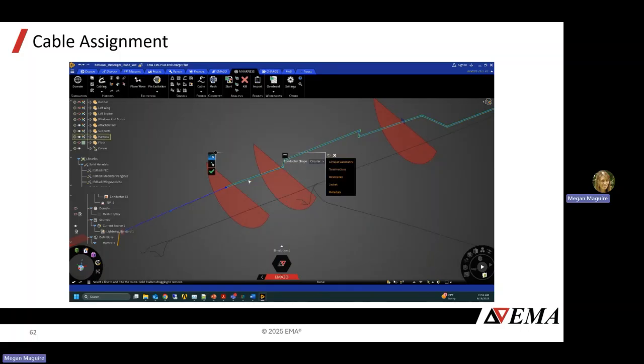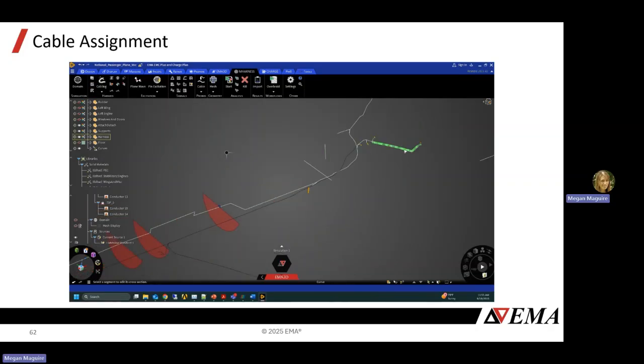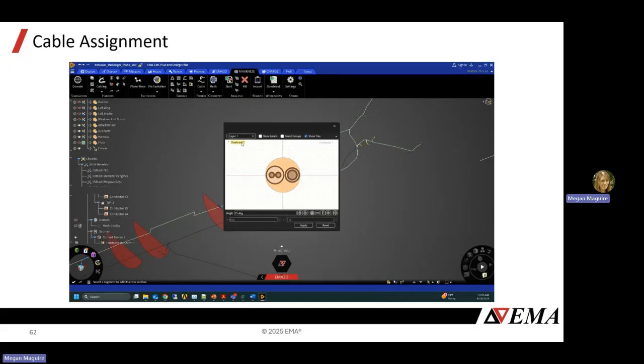Then select the lines in which that wire routes, in this case the same lines as the shield that we defined. It's going out to the empennage. Then select your termination points, in this case the beginning and the end, and not that bulkhead because we do not want the pin to connect there. Then you can copy the definition for your second pin, so you don't have to redefine each individual one.